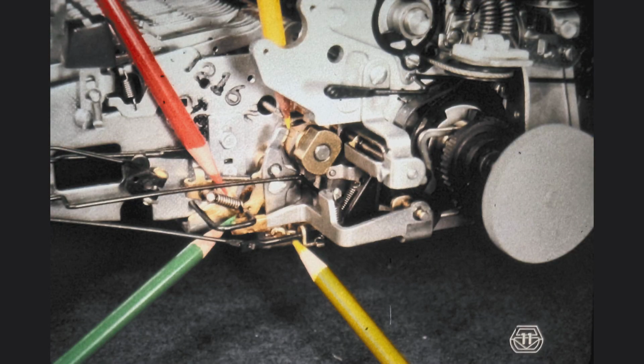The counterclockwise rotation of the low-velocity selector latch at the green pencil allows the spring indicated by the red pencil to make the low-velocity cam follower, or low-velocity actuator, follow the shape of the low-velocity mechanism restoring cam, indicated by the yellow pencil. Even a superficial examination of this setup will reveal that the machine must be in a character printing process in order for all this to happen.